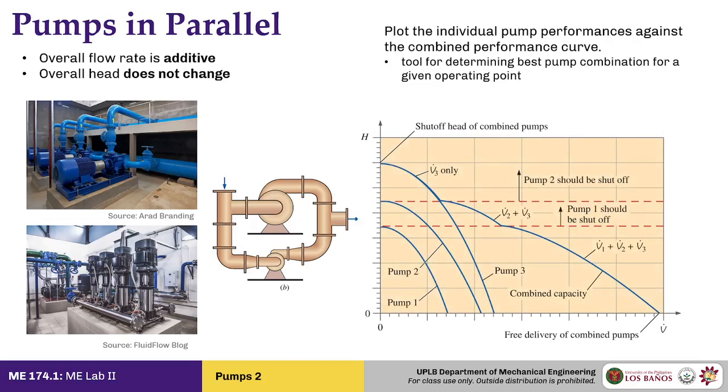So when you use pumps in parallel, your priority is the flow rate. You might have several weak pumps, like pumps 1, 2, and 3. And for one reason or another, you found that stacking pumps in parallel is more economical for you than having one giant pump managing that flow rate. So the source again is being meticulous. It has three pumps of differing stages. These pumps also have differing free deliveries and also differing maximum discharge heads.